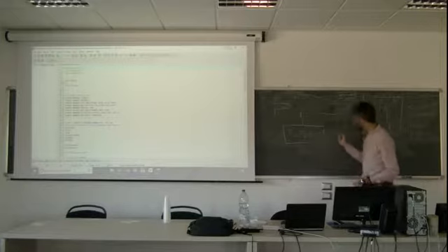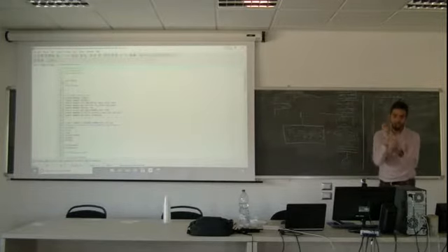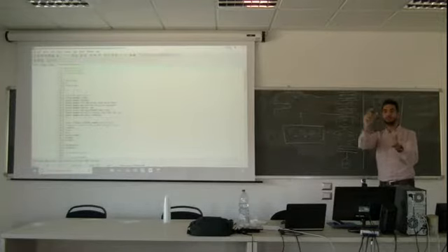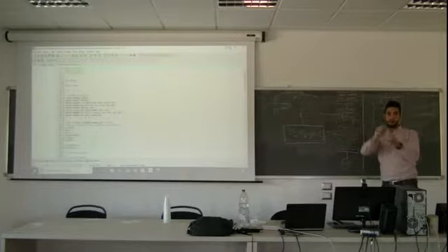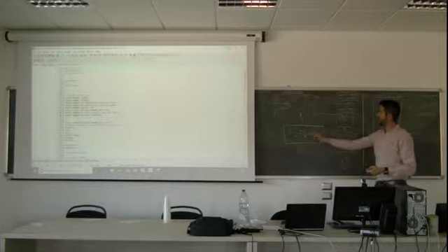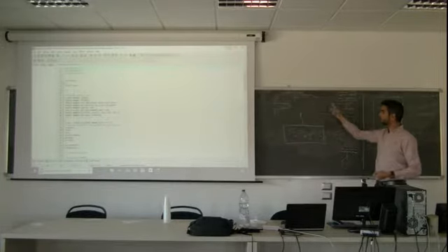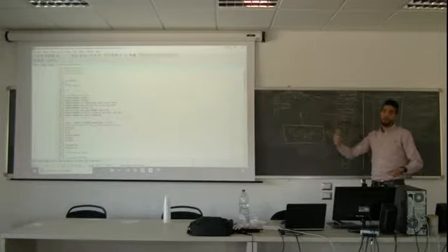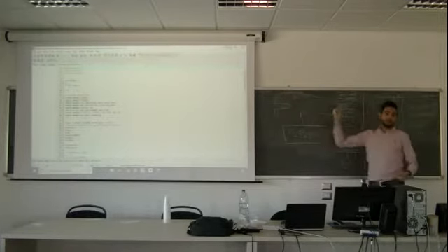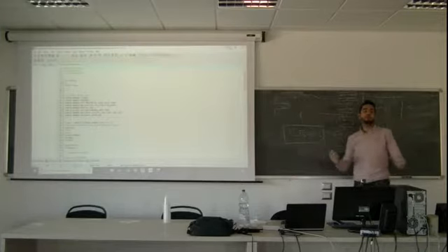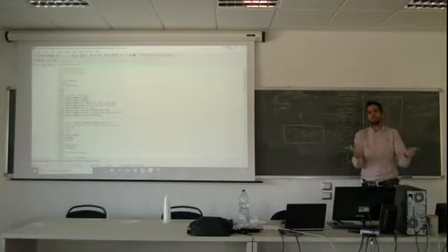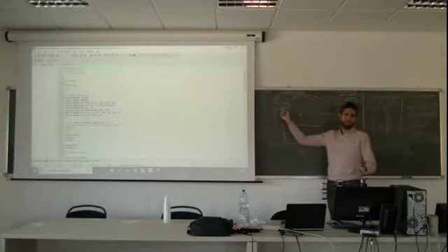For every iteration at every node, it has to compute the Nusselt number, and the heat transfer coefficient, depending on density, viscosity, and conductivity of air. And then it doesn't converge. Go here. No. Okay, another map of temperature, another set of heat transfer coefficients. Recalculate, recalculate, recalculate. So if you put a constant, maybe it's 1 second. If you don't, maybe it's 10 seconds. Okay, you can say 10 seconds is fine.